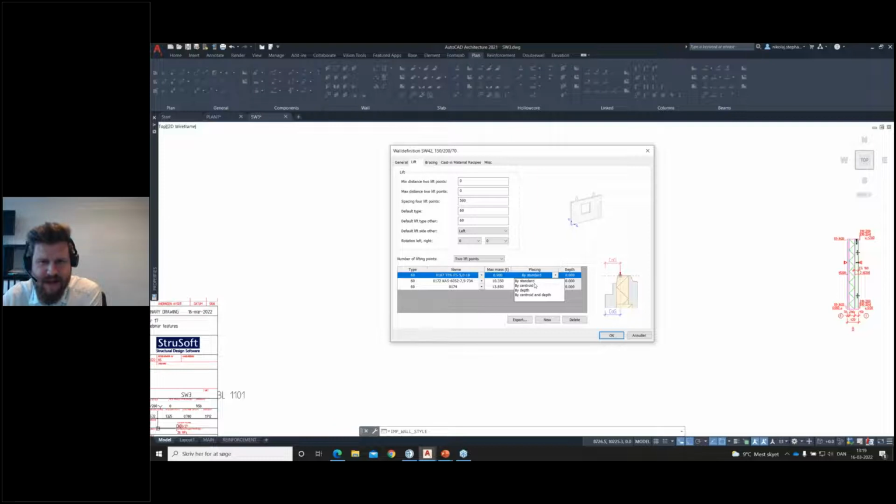But you now get the option of saying that I'll do it by centroid, which is standard in this case, or I'll do it by the depth itself, or I'll do it both by the centroid and depth placing. So what I've done is I did it by the depth itself, and I'm going to do it only up to elements that weigh 7 tons. When I get above 7 tons and up to 10.3 tons, I actually wanted to place this different type of lifter in it instead, and I needed to place it in the center of gravity. So we can check this by making the element a little bit bigger so it weighs more than 7 tons. So we'll just do that in a couple of minutes.